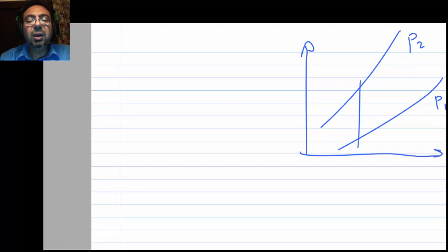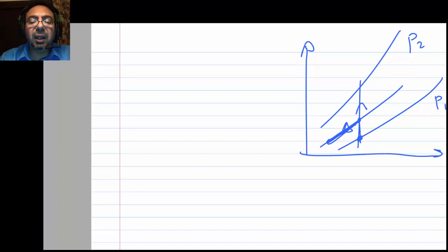So rather than going up like this, they will go up midway, and when they reach that pressure, they send the air to a heat exchanger. That heat exchanger will cool the air ideally to what? To T ambient. You cannot get lower than T ambient because you are cooling with T ambient.